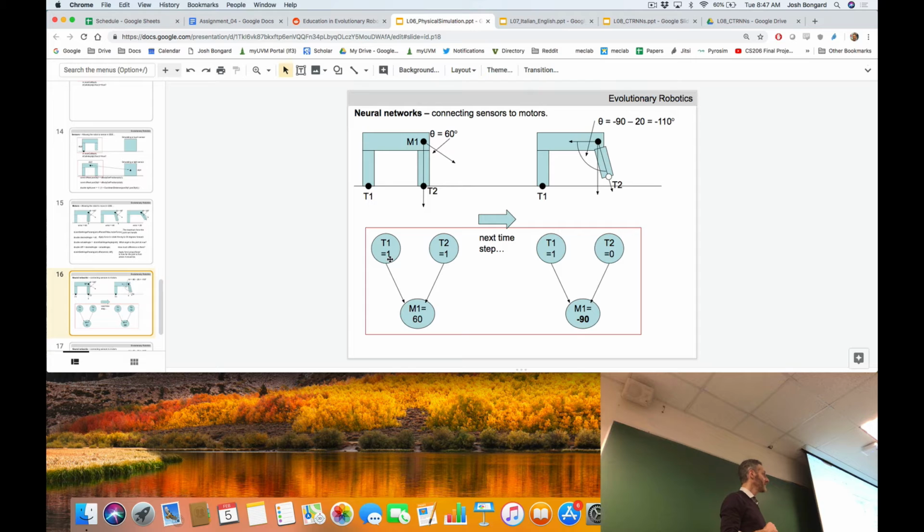This might be kind of a silly question, but is there like leeway in between where it like catches if it's rotating, or not really in a virtual environment? What do you mean by leeway? Like with some gear systems, if the teeth are not tight, it will need to like rotate before they catch each other and can start like turning the other direction. That's a good question. That's not simulated in the physics engine, but you can go in and make a more sophisticated motor. We're assuming that the moment torque is applied to a joint from a motor, it's going to apply force to the pairs of objects. How the acceleration of those objects changes depends on the other forces that are acting on the objects, like, for example, momentum.